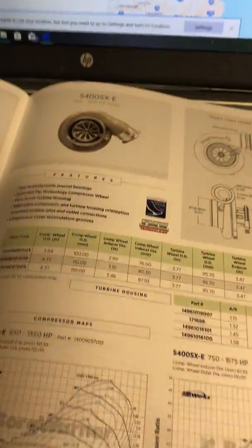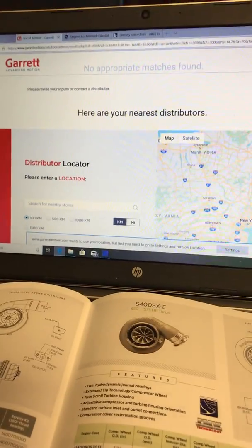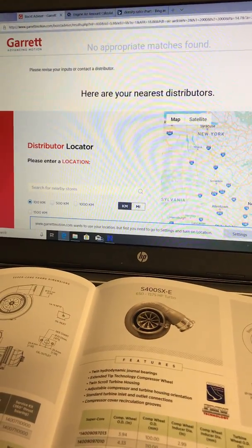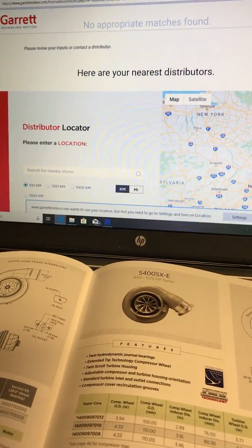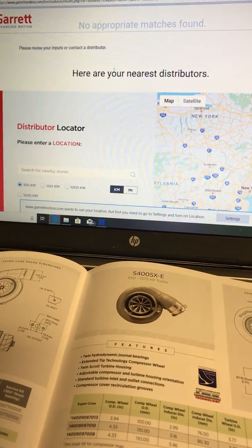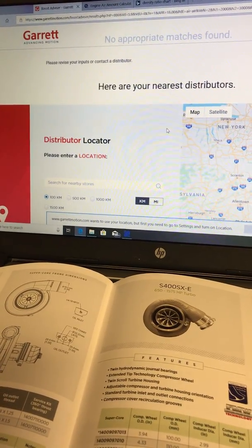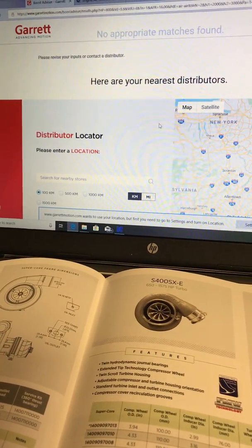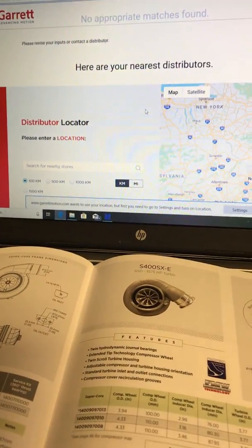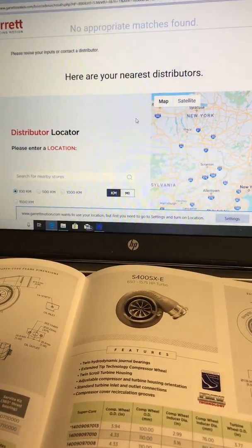I'm going to guess that maybe in the next video we'll go into compound sizing, really go A to Z. Or the other thing I might do is jump up to 4,000 or 5,000 RPMs on this 5.9 and show you the difference and how much easier it is to achieve more horsepower with 1,000 more RPM, because the big challenge is not 800 horsepower. The challenge is doing it at 3,000 RPMs.